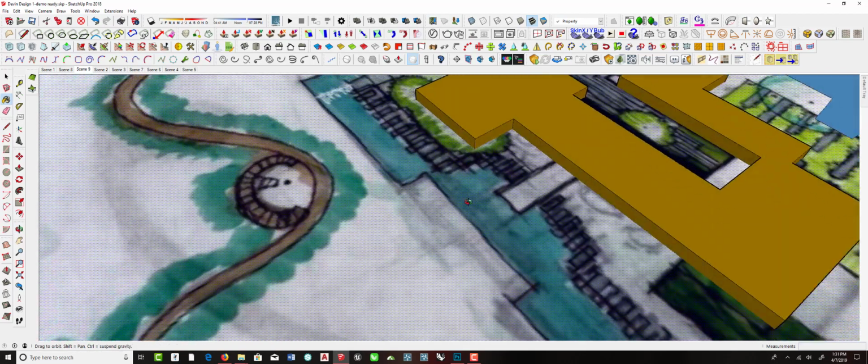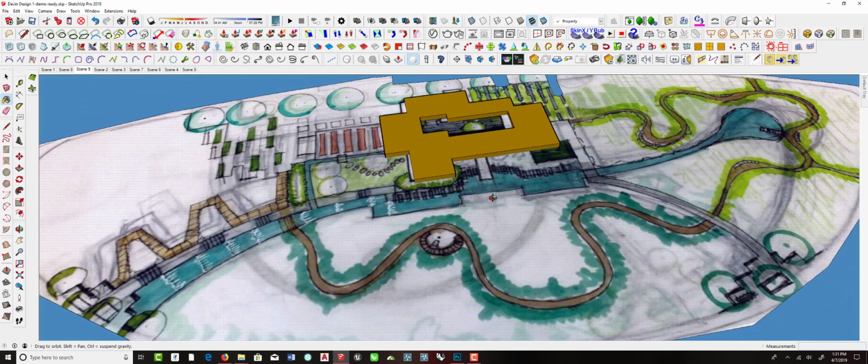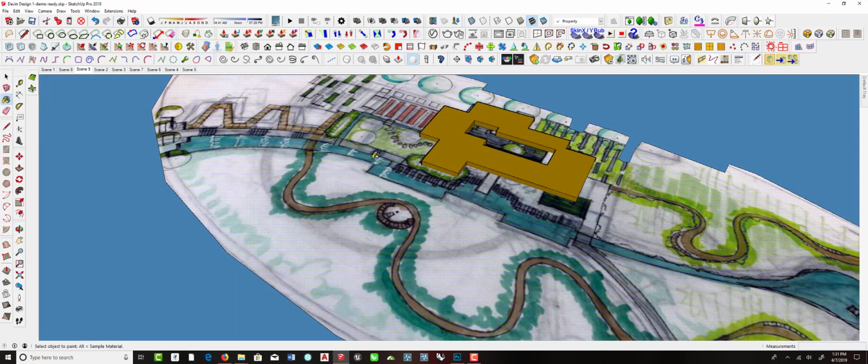Something has to hold this up, so there's probably a wall. There's got to be some thickness there. So those are all structures that, generally speaking, if they're level or if they're sloping uniformly, I would model right off of this 2D surface, create groups out of them, and then drop those down onto the terrain model and manipulate the landform to match those as best as possible, and manipulate the structure to match the landform. But you go back and forth.